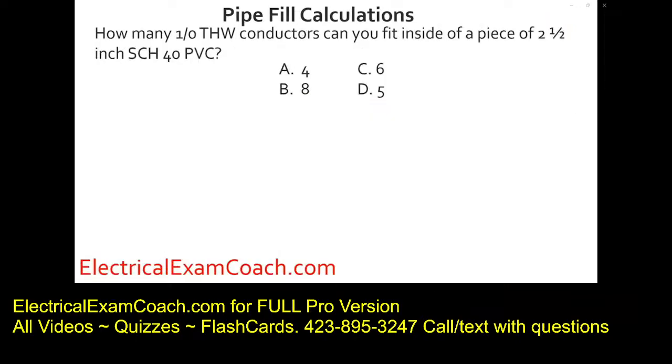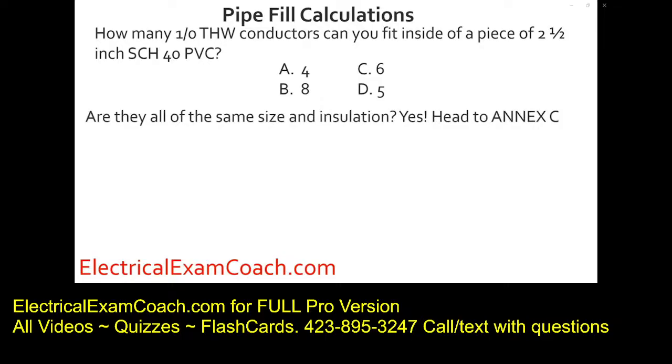How many 1/0 THW conductors can you fit inside of a piece of 2.5 inch Schedule 40 PVC? Are they all of the same size and insulation? Yes, so we're going to head to Annex C.